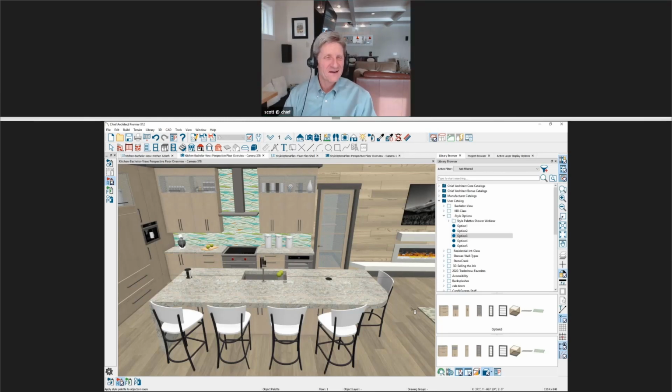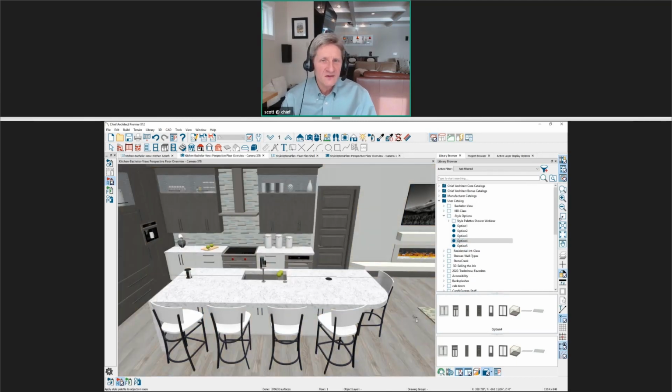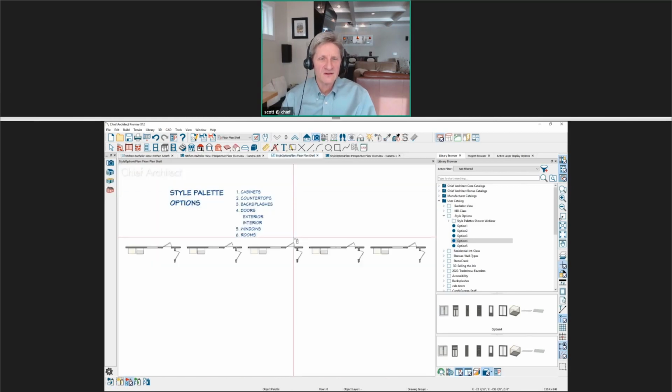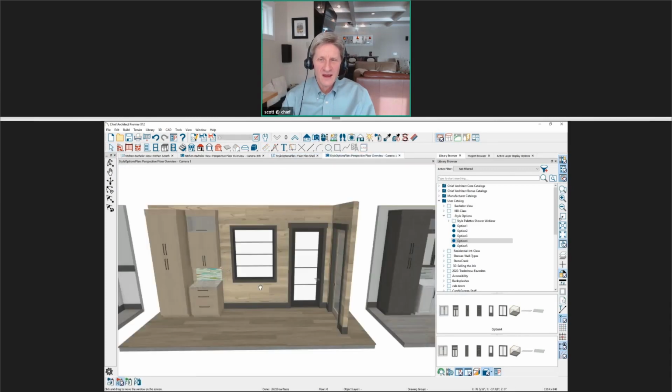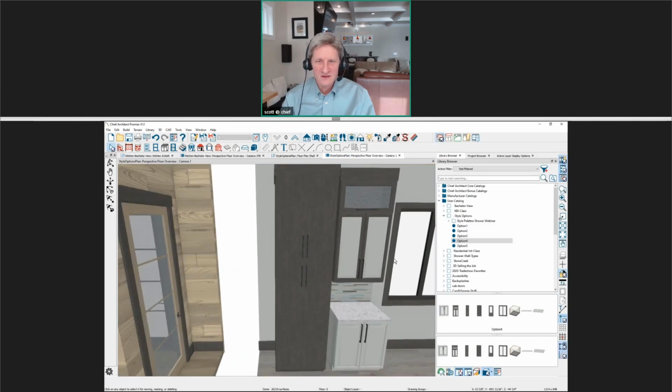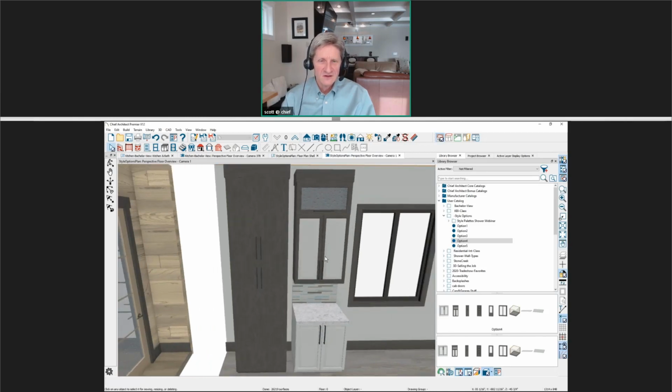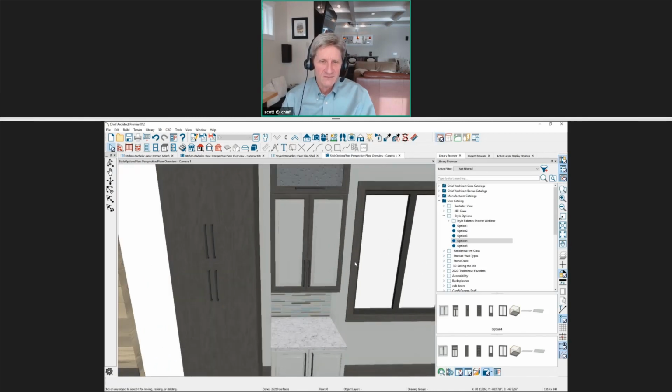Do you like that? Yeah, I do. Oh, the door styles, would that just be an object wrapper? Yeah, and so the door styles, in this example, when I apply this, you'll notice that the door style is a little bit different. Let's go back into this plan because I probably have changed it. And so any one of these door styles, you can set it up and change it. So you see how I have a different door style in here? Mm-hmm. Yeah, so you can build those.